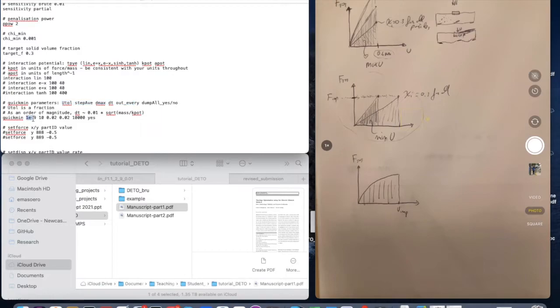This is the tolerance. So the Quickmin is considered as converged, so the system is in static equilibrium, when the particles, as they move and rearrange under the imposed displacement, don't change the internal energy by more than 1/1000th of the previous value. So it's a strict criterion to say the system has converged to a static position.